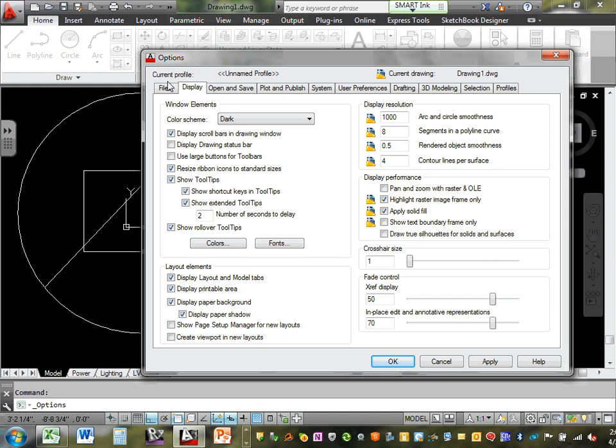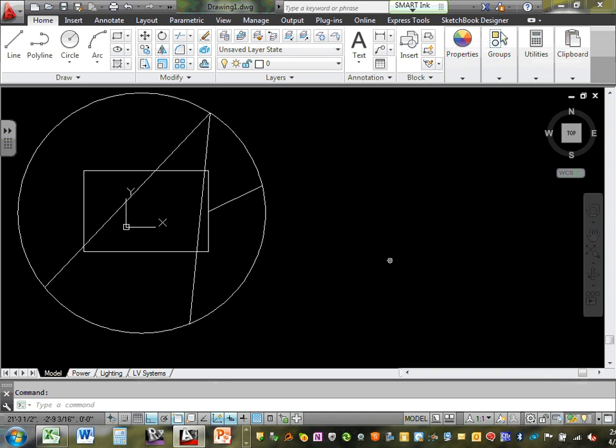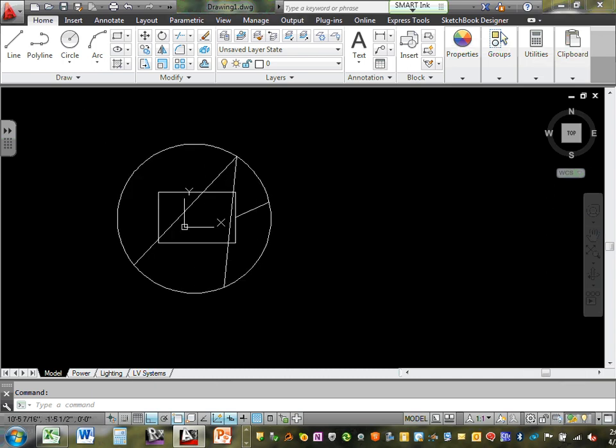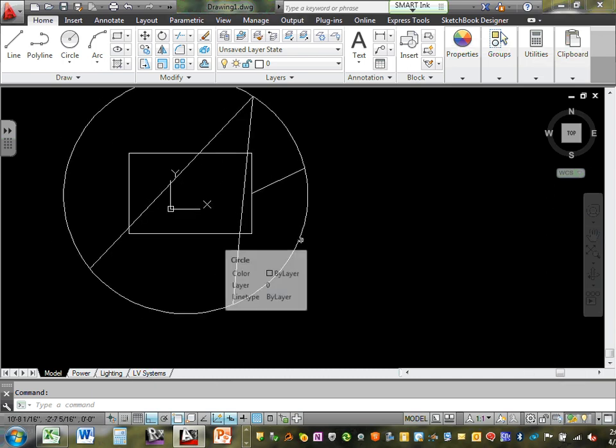But there are a lot of settings in Revit. Go to the options, and you can find a lot of things you can set for CAD to look the way you want it to look. Does that make sense? Always click the big A, options, and dig around, and you'll find a lot of settings. Make sure you hit apply and or OK and get out, so it's applied.